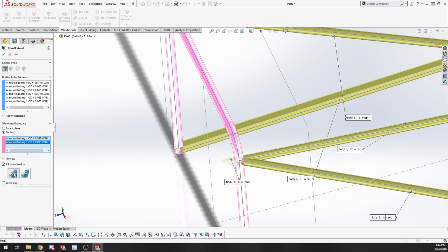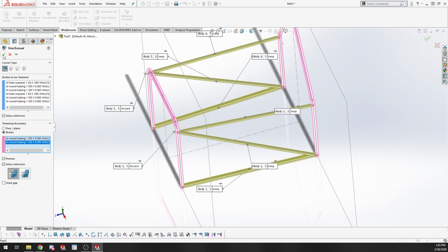Usually what we want is actually this. Because when we're welding, we need room for that weld bead to penetrate and bond to the material. If it's right up against it, we're welding on this really tiny, thin piece of metal that isn't actually cut. So we want to cut it flat, leave some room for the weld bead to penetrate in there, and weld to the full thickness of the tube instead of just that little tiny flappy bit sticking off. Cool. So that's one of our trims.